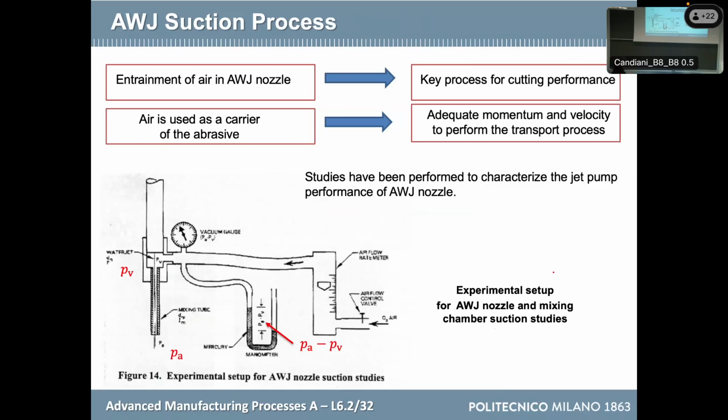So there are many ways of measuring everything. So again, this way I can monitor the process. I'm telling you that we can use two other sensors. One is the vacuum pressure here that is really capable of detecting if the cut is good or not. And then the flow meter.